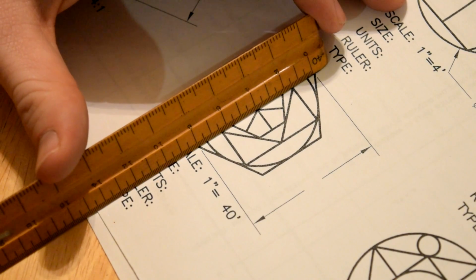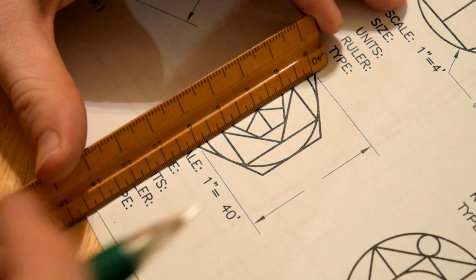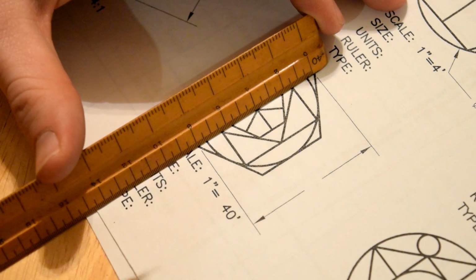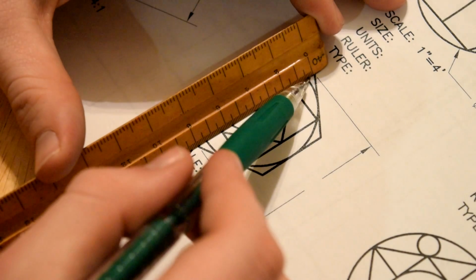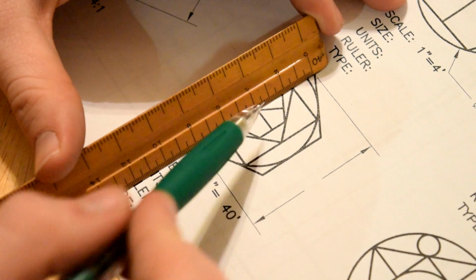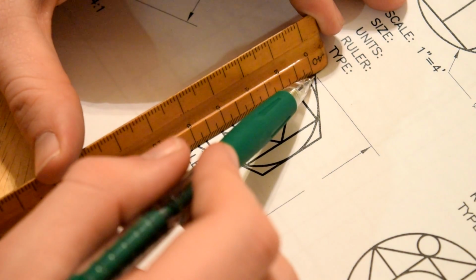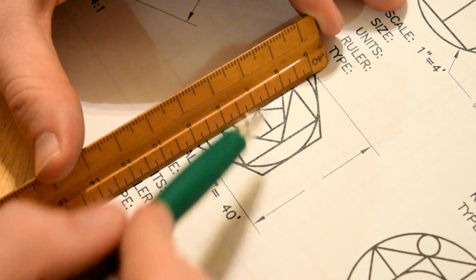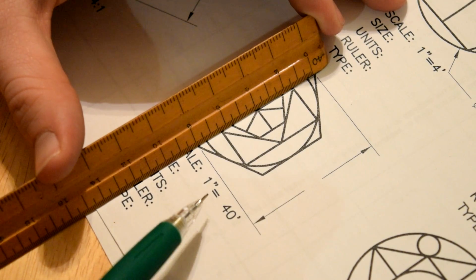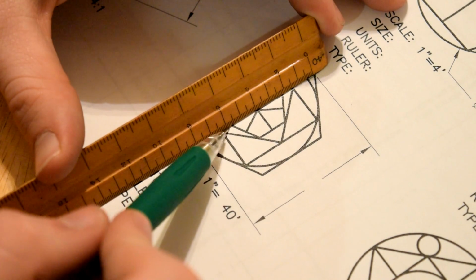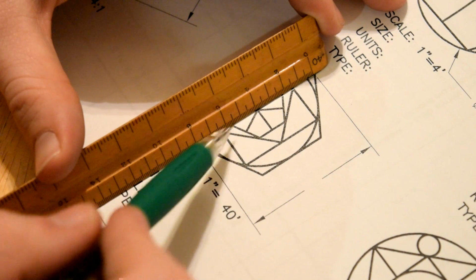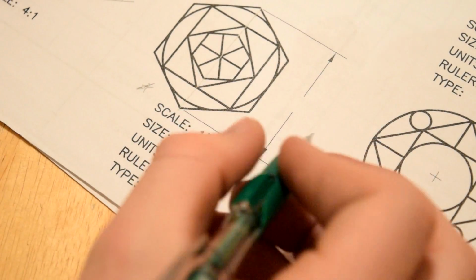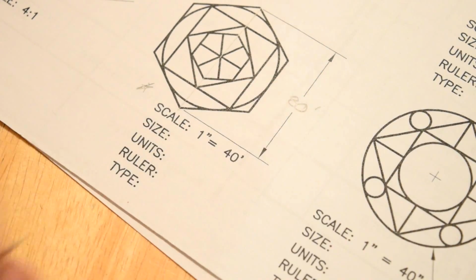So it looks like if I keep one point at one end, so 0 is at this end, I'm lined up exactly with the 8 here. So we know that 1 inch, so we come out to the 4, an inch on paper goes from 0 to the 4 here. We know that that's 40 feet according to our scale of 1 to 40. And since this is 2 inches in reality, come out to the 8, so that's 80 feet. So the size of this dimension is 80 feet.